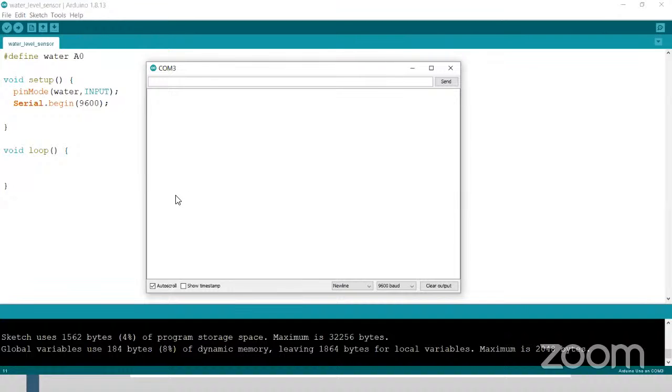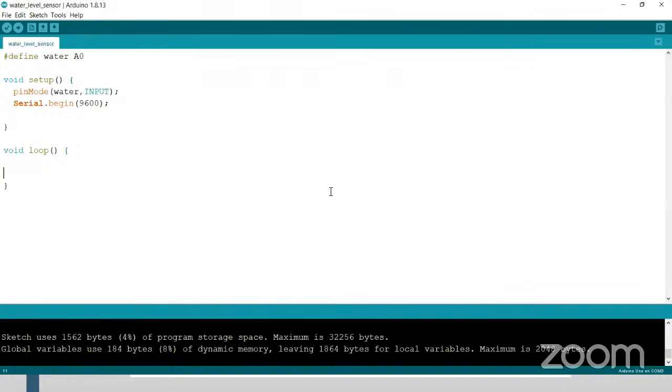Okay. First, I will fix that sensor, like water. I will fix the one analog sensor, so I will give the analog pin initialization. Then the sensor will be the input. I will tell the controller that the sensor is the input via the pinMode function.